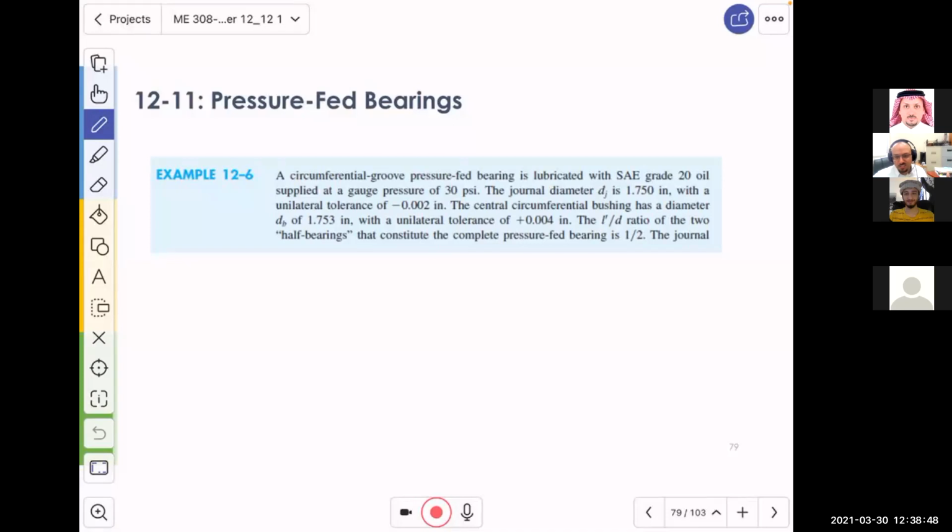But essentially everything is the same. It's just different numbers, different unit, different size, but then you reach the same conclusion. And from where did we get those numbers? Raimondi and Boyd spent tons of hours probably trying to juggle this Reynolds equation, unsolvable equation. It's not unsolvable, by the way. It's not solvable analytically. So I want you to think about